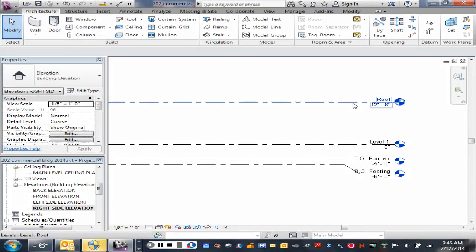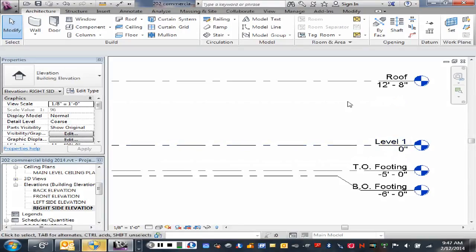That's a parapet. So let's assume commercial construction, we want to have, what ceiling height would you recommend? 10 feet, okay? Somewhere around 10 feet. It could be slightly under 10 feet. And I'm not going to be specific with you. It's up to you, but let's not go anything less than, let's say, 9'6", okay? But you could have a 10-foot ceiling. You could have a 12-foot ceiling. Whatever you want to have, it just means your outside walls are going to get taller, right? Okay, so let's just assume that we're going to have a ceiling height of 10 feet.